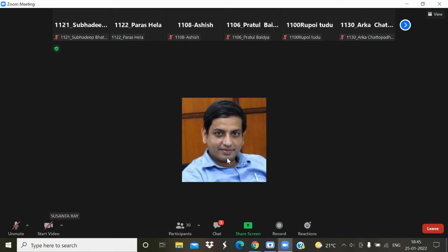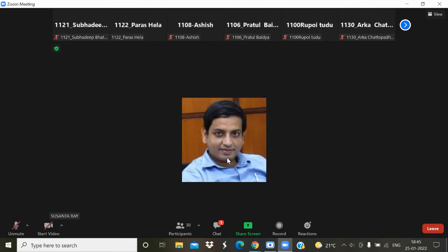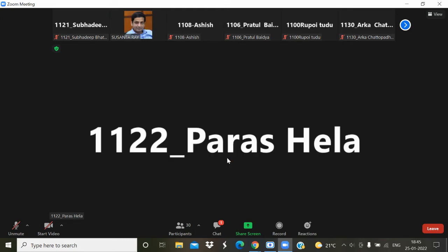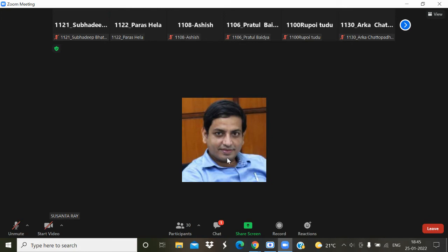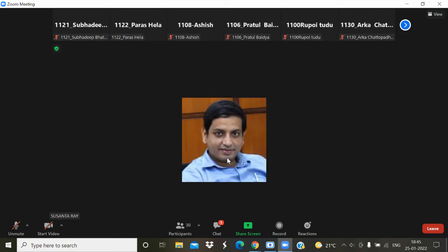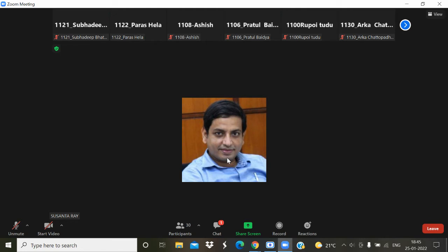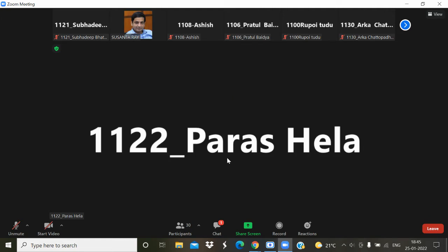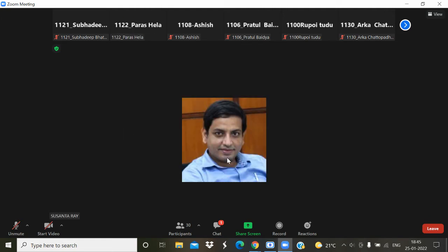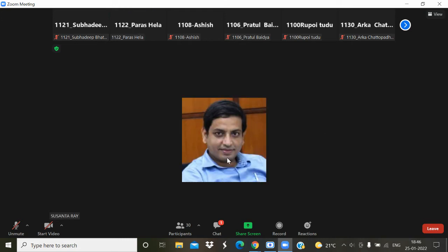Okay, so Parosh, you write down your specification. 60 kilowatt, 415 volts, 1000 RPM, squirrel cage induction motor, delta connected, 88% efficiency, 0.86 power factor.